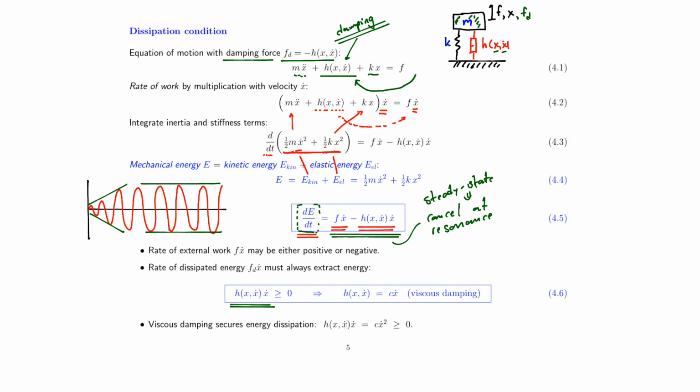And that is not in agreement with the device to be reactive. That requires external powering. So if your damping device does not dissipate energy for all time, it will actually add energy, and that requires an external power source, and what we will refer to as active control. And we're not going to consider that in this course. So we will, for all our damper models, always consider this quite important dissipation condition that should be fulfilled for the damping models that we consider.